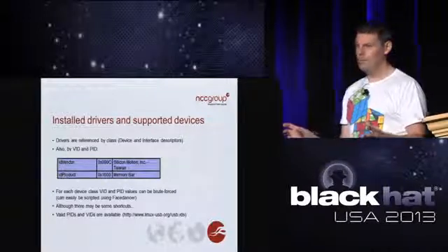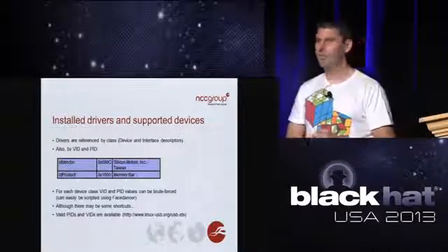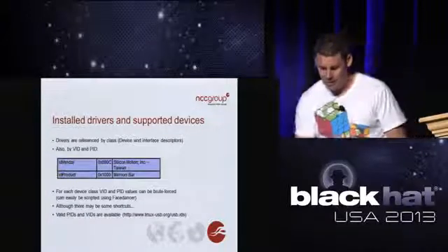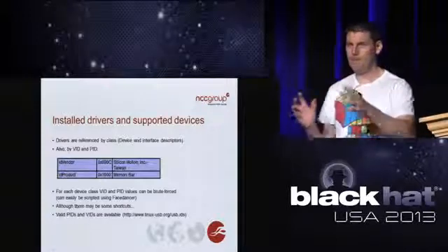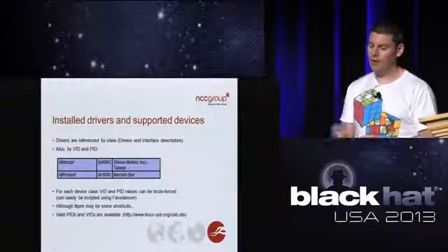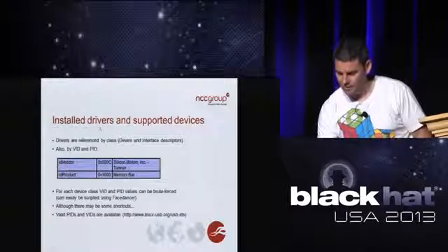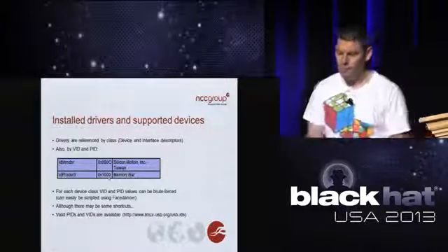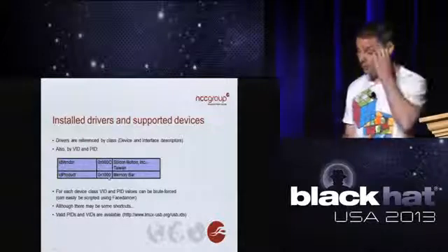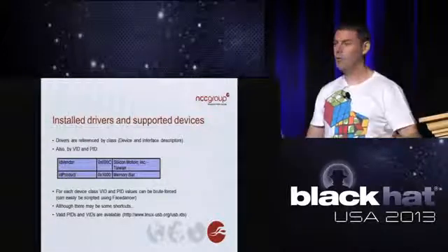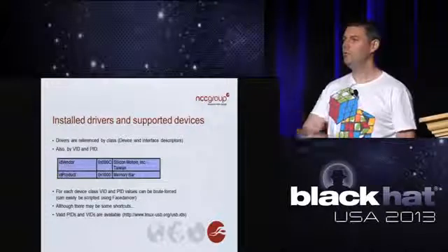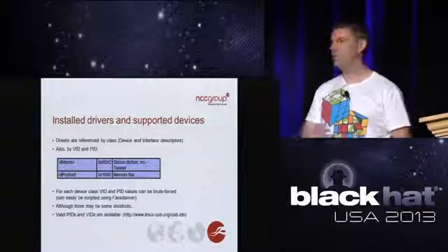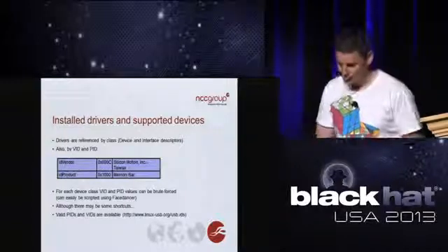When you're talking about specific device drivers that have been installed rather than the generic ones that are available, those are indexed via the vendor ID and product ID, which are these 2-byte values which are provided in the device descriptor. So the vendor ID and the product ID basically map to the class driver. Once enumeration has finished, it then loads that driver, and you know that class communication can occur.